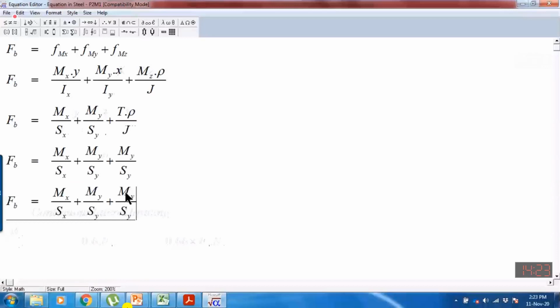So if I multiply it by 2, these are the total bending stresses. Or you can bring this to the bottom. You can assume that Sx, the section modulus about the x-axis, takes the moment about the x-axis, but we use half of the section modulus about the y-axis for My, and half is reserved for the torsion.